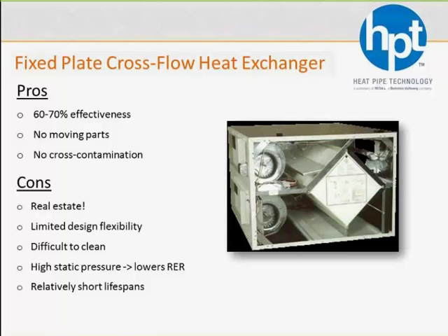Downsides, however, probably the biggest is just they take up a lot of space. Most cores max out at about 5,000 CFM, so if you have a high volume system, you need a bunch of those cores, and they're not small, so you have to make sure you have plenty of space for them. They're not very easy to clean. From a maintenance standpoint, they're not moving, so that concern is out of the way, but they're not easy to clean.